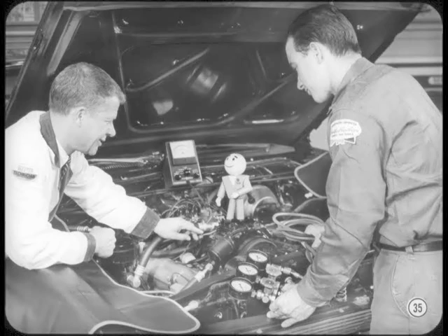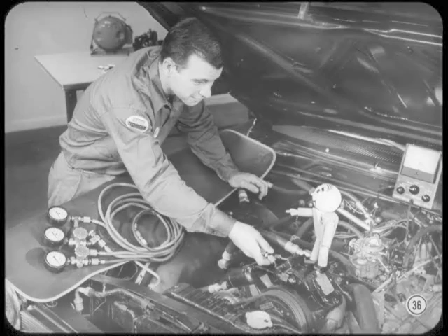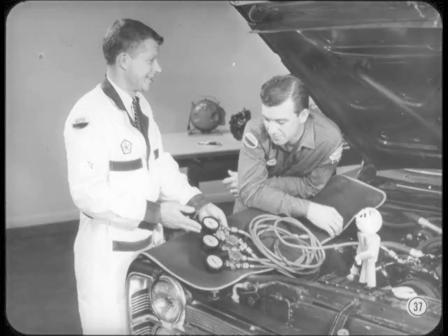Now, no matter if the refrigeration system is charged or empty, you'll need the gauge set for either testing or recharging. So first, we'll connect the gauges and see whether the system is charged or empty. Be careful how you handle those gauges, Ken. If they're dropped or banged around, the shock can throw their accuracy off. If a gauge is off only a few pounds, it can mislead you into replacing good parts or the wrong part. Gauge accuracy should be checked at least once a month so you can rely on the pressure indications.